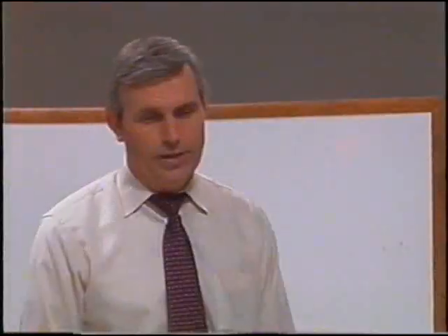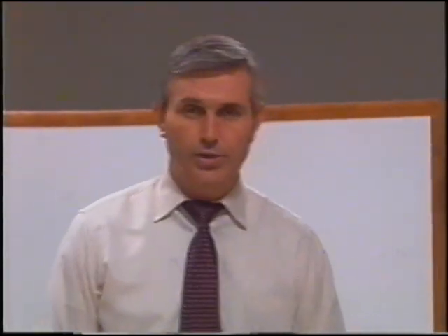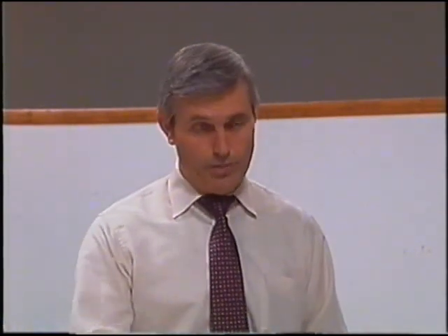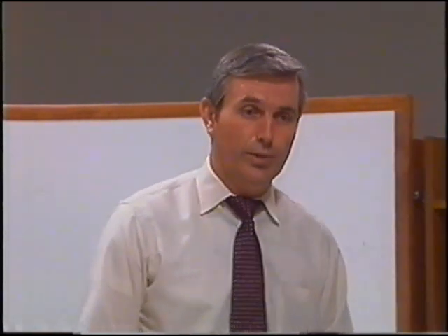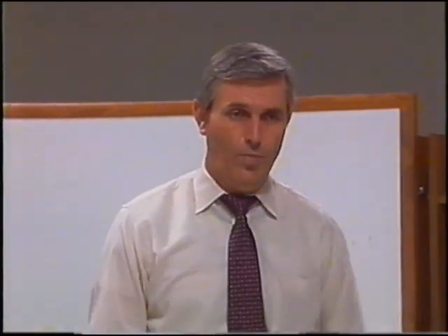Yes, John? You said that these fingers are caused by little perturbations at the front. Right. What might cause these little perturbations? Oh, it takes hardly anything. Actually, there's some evidence accumulated now to suggest that it takes some random perturbations, but they don't have to be of great magnitude. Certainly perturbations of the order that you would encounter in a core. Such as heterogeneities? Heterogeneity, yes. Heterogeneities would do it. Anything that causes one point on the displacement front to get out in front of another point.